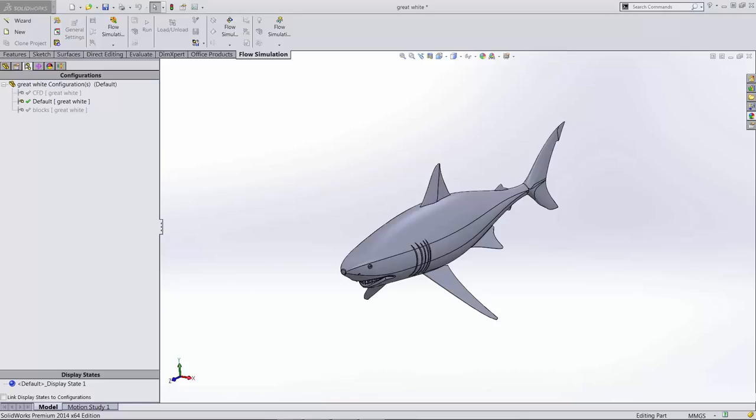One of the shark's greatest assets is its speed in the water. A major factor in this is its drag coefficient. This is the same principle that works for air flowing over an airplane wing or a car. We usually refer to something that is sleek as aerodynamic. In water, the appropriate term is hydrodynamic. Here we'll be analyzing a 20-foot great white swimming at 25 miles an hour. This is the maximum speed of travel and where drag will be the greatest.